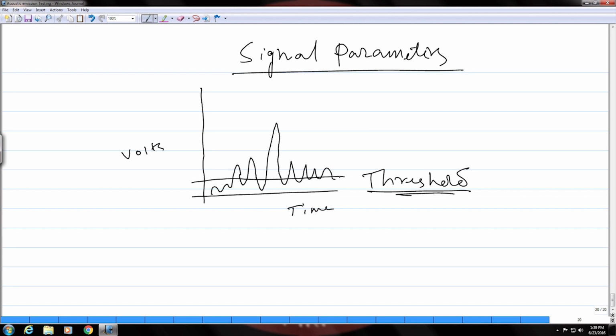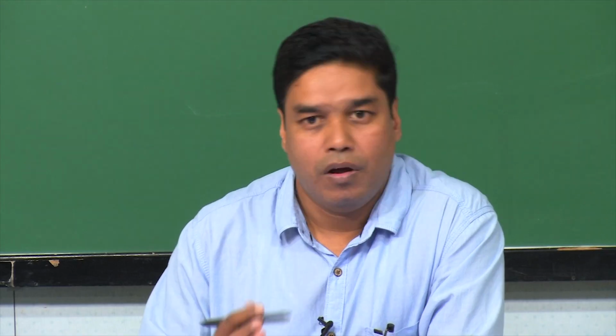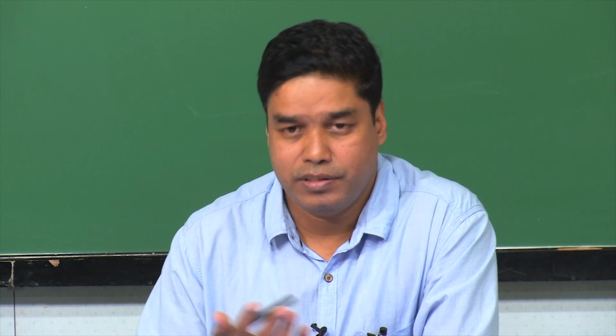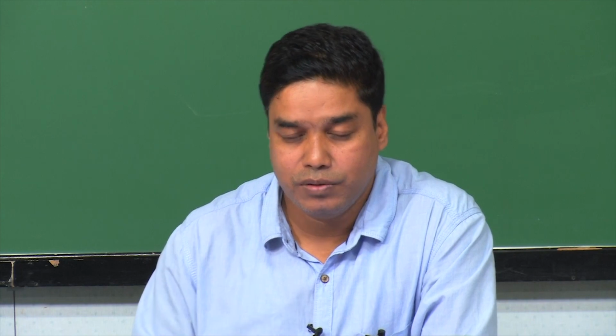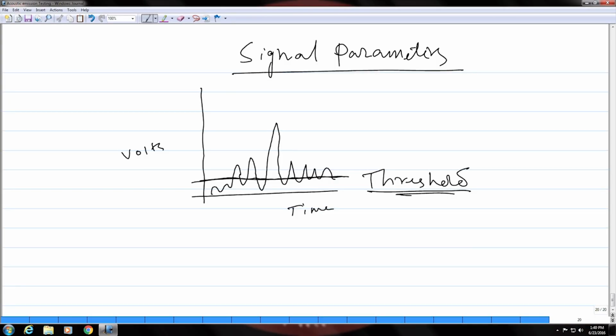Okay. So, you could see a signal like this. Whatever is above this threshold, which is generally user defined based upon the experience of the user or the part being examined, is considered as acoustic emission events. So, from this signal you can define certain signal parameters which can be used, as I said, for doing acoustic emission testing.